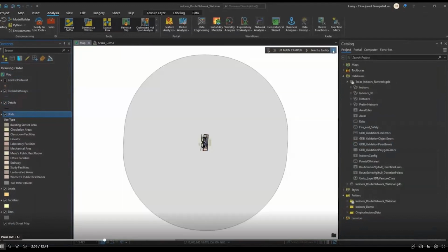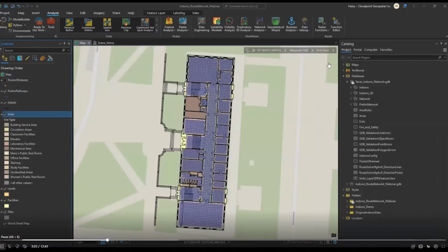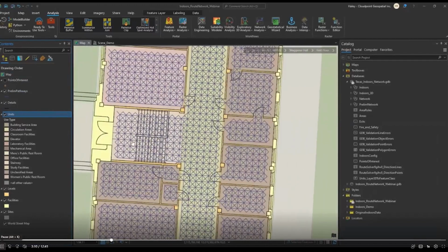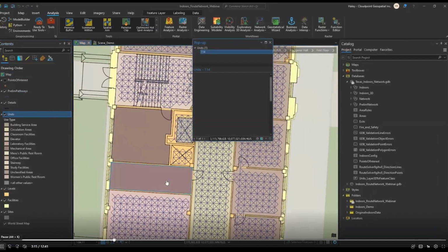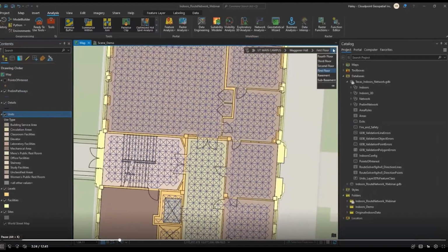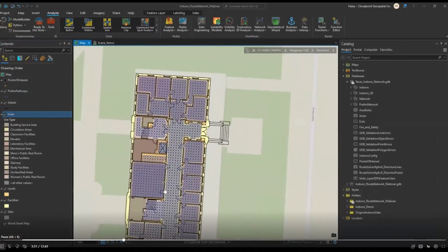We'll go to this, University of Texas, Wagner Hall. And now we're just seeing the first floor. Now you want to make sure that it created what you wanted. As you can see, it's avoided the walls and the columns and also that mechanical area that I had specified. All the pathways are going through the doorways, which is good. And then you can check different levels to make sure those worked. So now that is looking good.